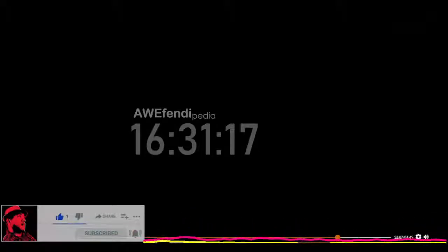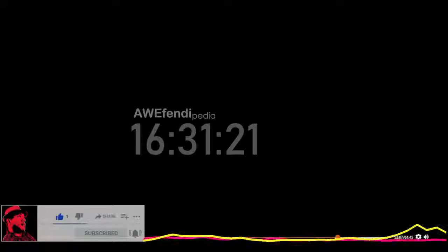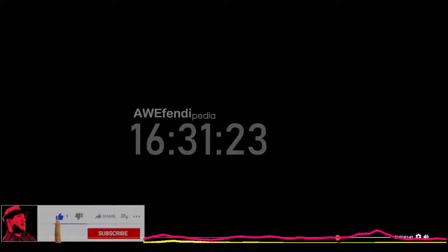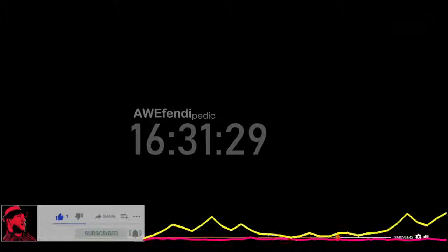And we'll do that same for this bridge pier, change the field code to BRGP, and hit enter there, and it makes our triangulation look a lot better. Okay, so our triangulation looks good.